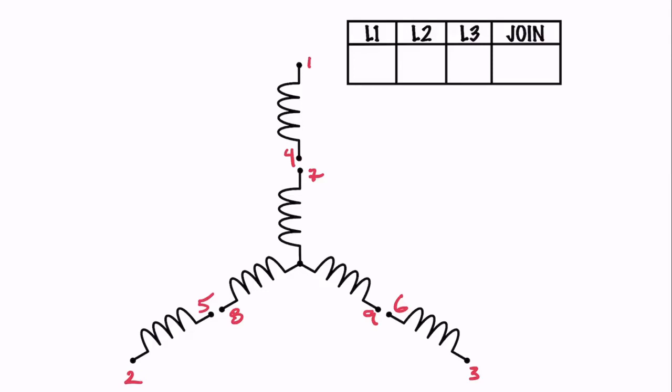We just know that if we've got 230 volts here and we want to get 460 across it, each winding is rated at 230. We're just going to connect them in parallel, or sorry, we're going to connect them in series. So that becomes very easy. Watch this. We're just going to go boop and boop and boop, right? So we got those connected.